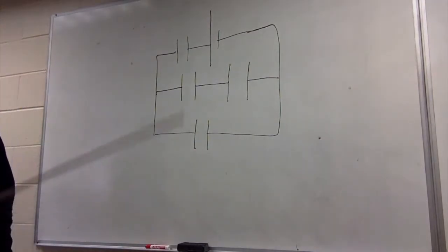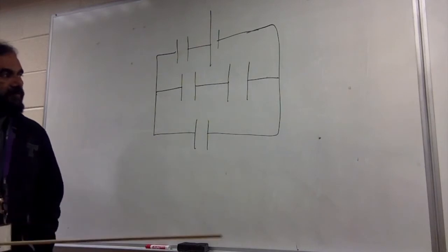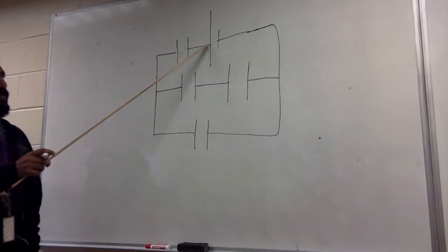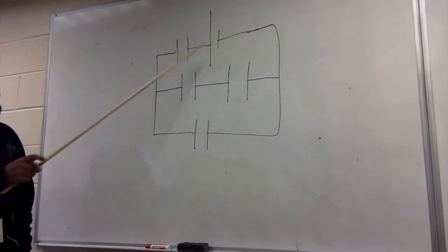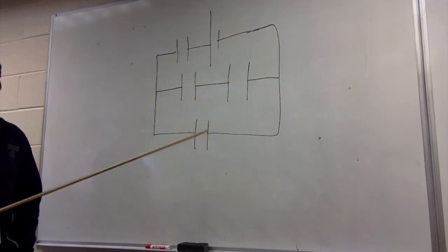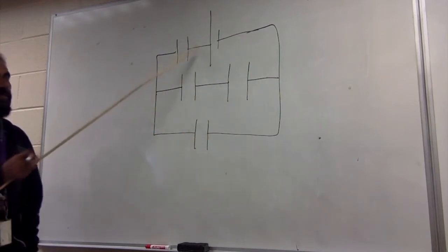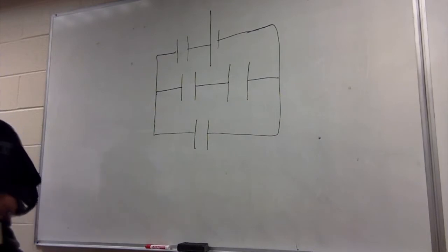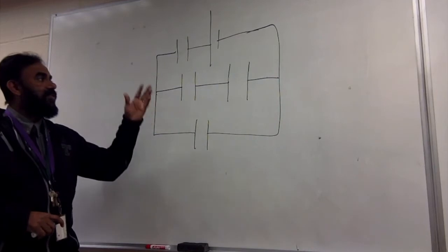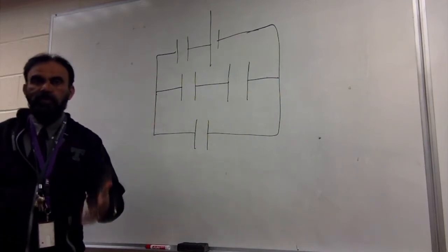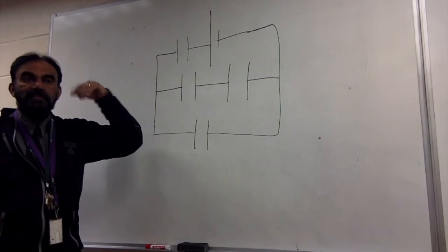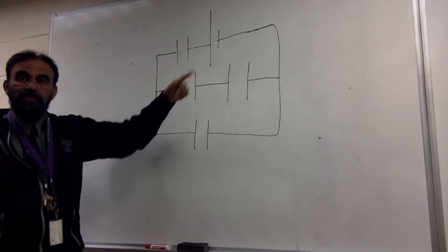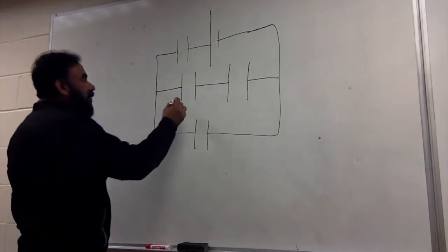Okay, so when you have capacitors connected to a power supply, a load of charges will be delivered by the cell to charge all of these. But after waiting a little while, what will be the current in the circuit? Zero. After waiting for a while, the current will end up zero, because once all the capacitors are charged as required, there's no more charging current, because all these have built up a voltage which is equal to the power supply voltage. So let's do this.